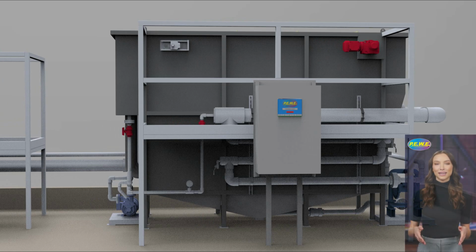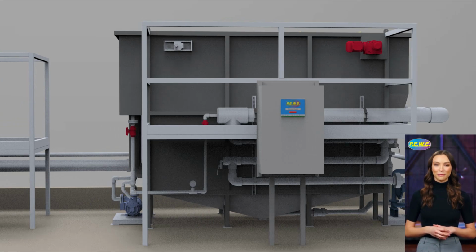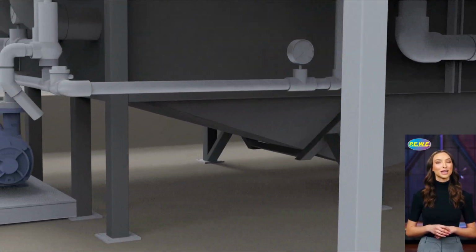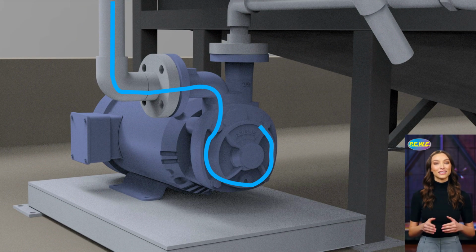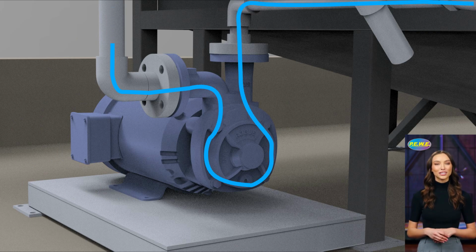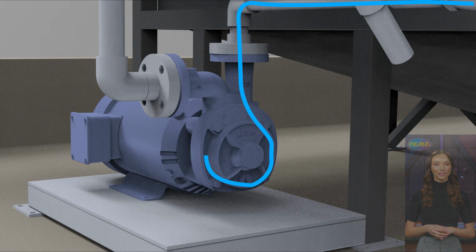The wastewater first enters the pipe flocculator, where the chemically pre-treated stream is combined with aerated recycle water generated by a regenerative turbine pump. This system produces extremely fine air bubbles in the 20-30 micron range, which attach to the particles and reduce their effective density. The air-laden mixture then flows into the unit for separation.